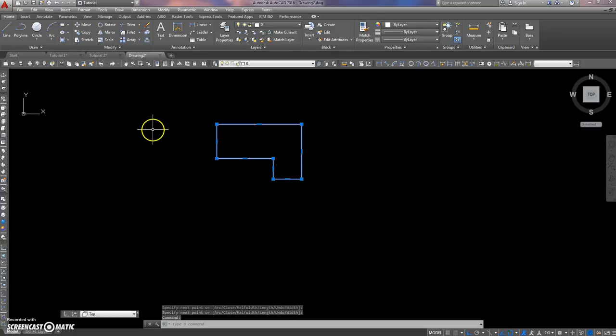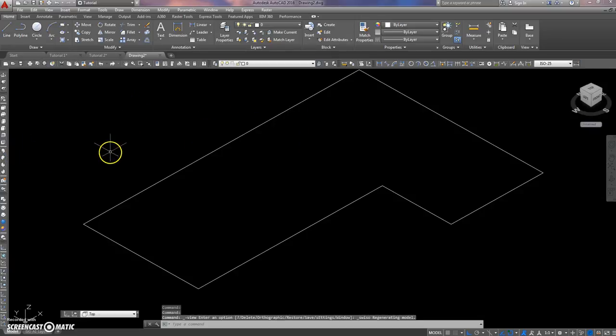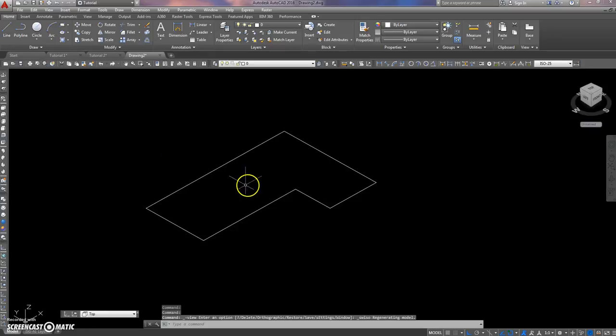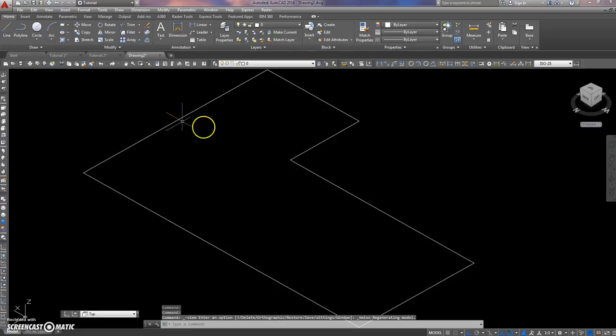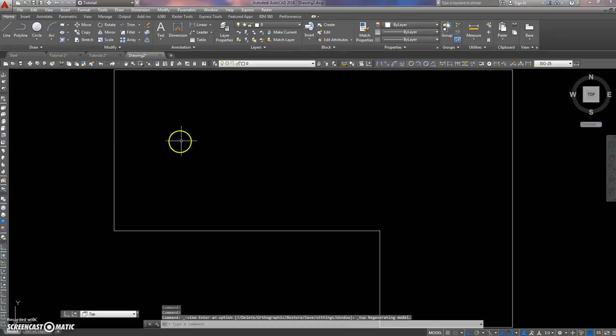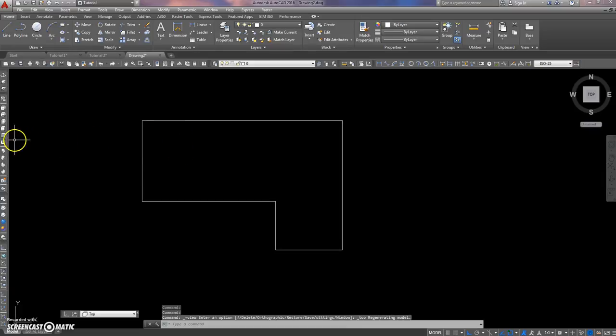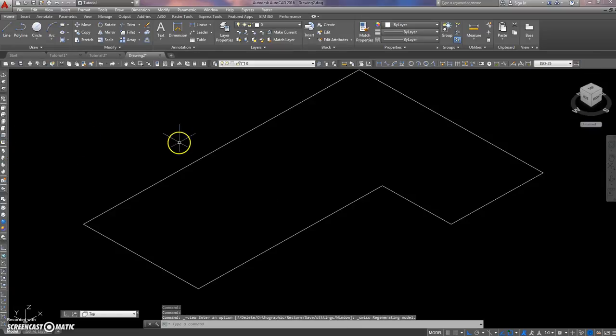And everything is always in 3D, even though when you're drawing in 2D, you think you're drawing in 2D. In actual fact, you have been drawing in a 3D space all along, and there it is. You just click on there, and it shows you the southwest isometric view of that. And you can look at it from that way, or that way, or that way. That's very handy. And then when you want to get back to a plan view, you just hit top. So there we are. We've got our piece of floor.